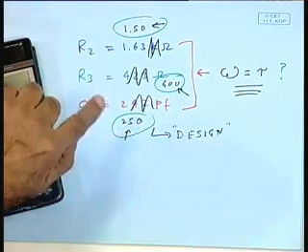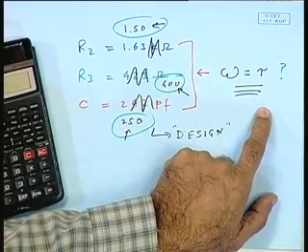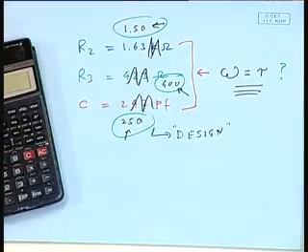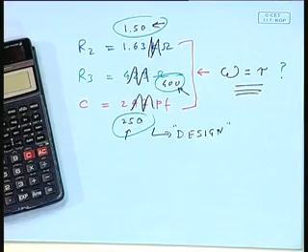You can allow these changes and still this will stay there, provided this performance has been made robust with respect to the choice of these values there. If you could do that, you've got a robust design. You've created a robust filter that will still give you that cutoff frequency that you want, and at the same time it will allow you to go to the market and buy the components that they have as standard components. This is like a big jump in terms of the utility of what is available to us. At the same time, we are guaranteeing we are staying pretty close to whatever we wanted to do, which is like staying close to the target at which the cutoff frequency should be. Let's see how we did that.